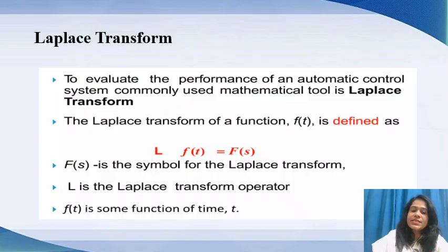Laplace transform. Solution of any physical problem can be obtained by the time domain approach or by frequency domain approach. The conversion of time domain to frequency domain function is known as the transformation. The reverse process is called the inverse transformation. There are two types of transformation: Fourier transformation and second, Laplace transform. But I want to discuss here Laplace transform.